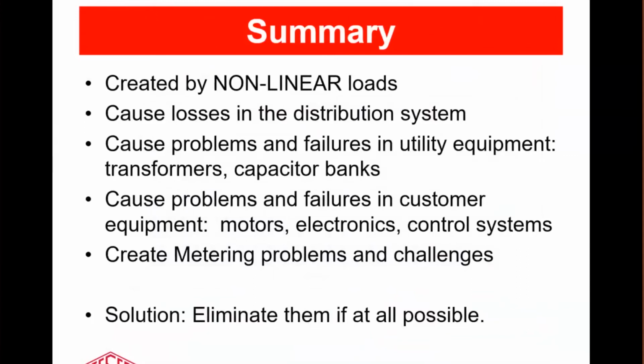So, summary. Harmonics are created by nonlinear loads. They cause losses in the distribution system. They cause problems and failures in utility equipment, transformers, capacitor banks, and they cause the same sort of problems in your customers' equipment, in their motors, their electronics, their control system. They create metering problems and challenges, not the least of which because our standards haven't caught up to the technology.